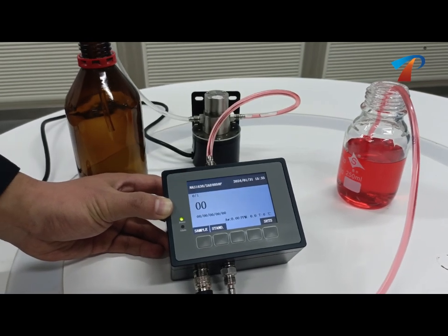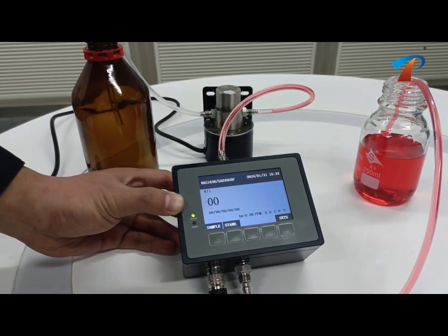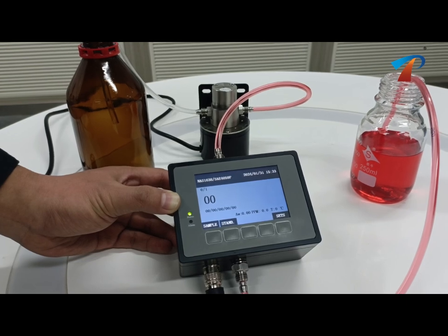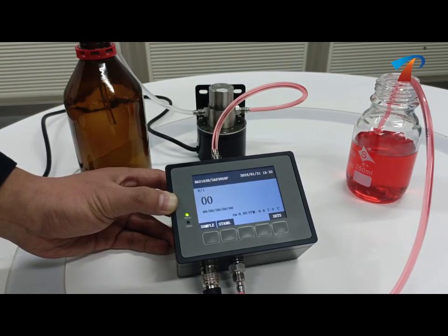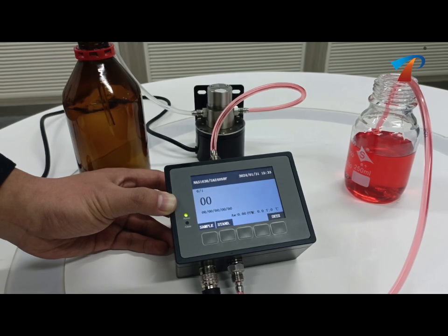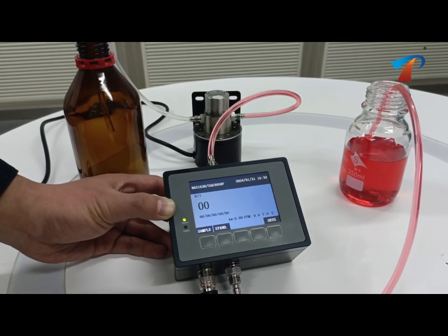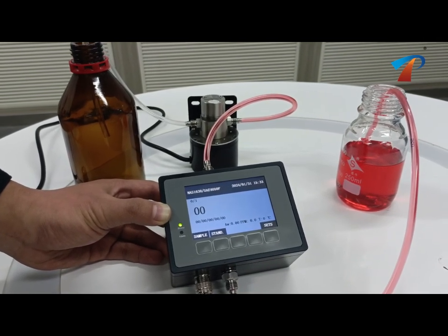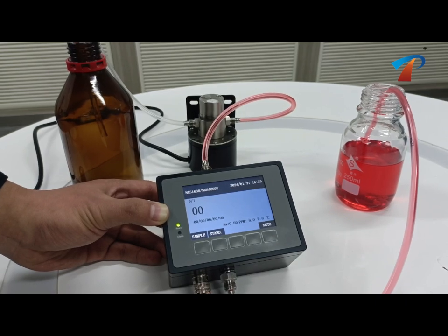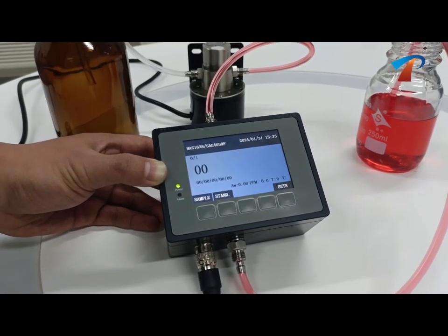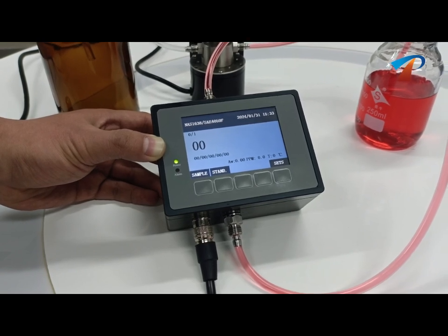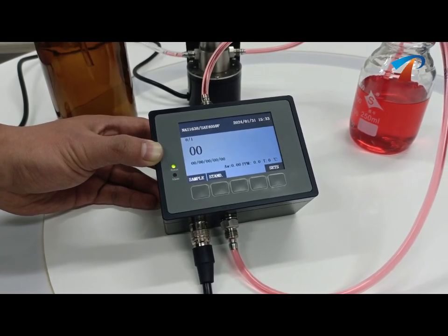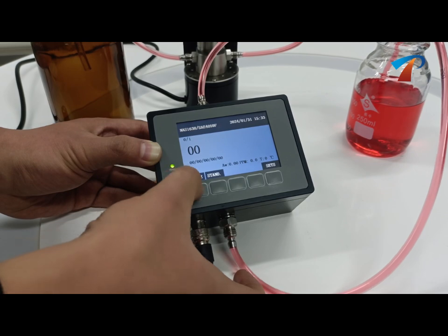During the testing of this online equipment, it needs to be connected to the pipeline and tested through the power source. We prepared the pump, waste liquid bottle, and treated oil sample in advance. Connected the equipment with the connector and pipe, put the liquid inlet pipe into the oil, selected the corresponding standard, started the pump, and clicked Start.